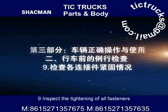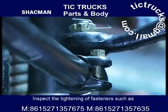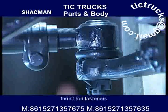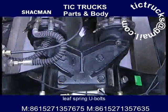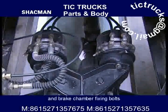9. Inspect the tightening of all fasteners. Inspect the tightening of fasteners such as steering knuckle rocker arm nuts, steering gear universal joint nuts, tire bolts, thrust rod fasteners, tie rod ball pins, leaf spring U-bolts, brake chamber bracket bolts, and brake chamber fixing bolts.